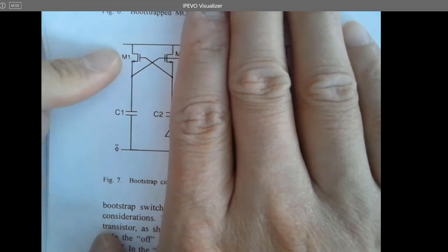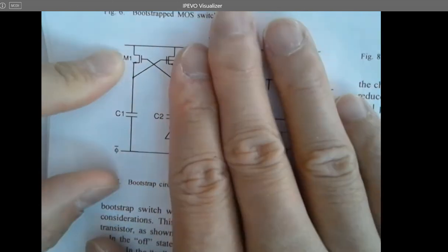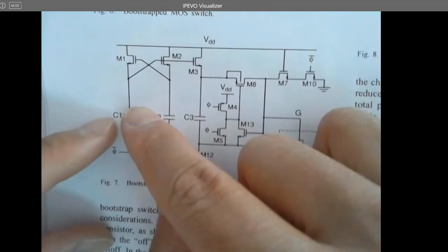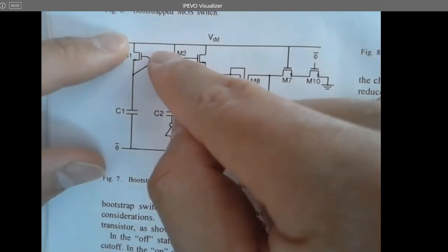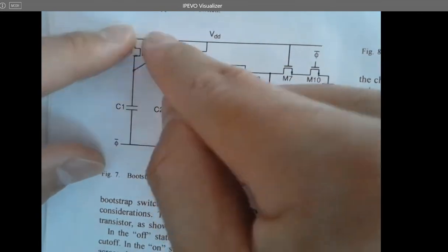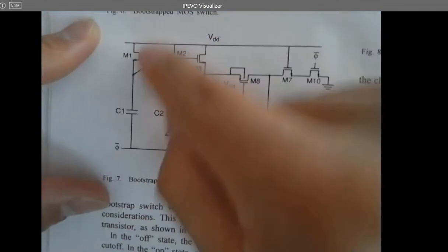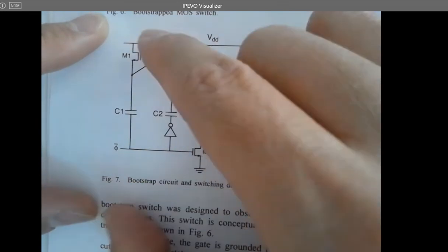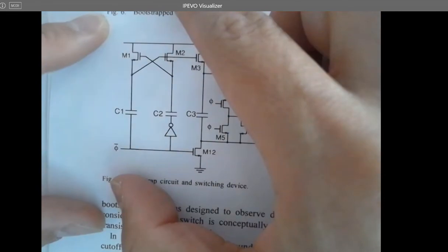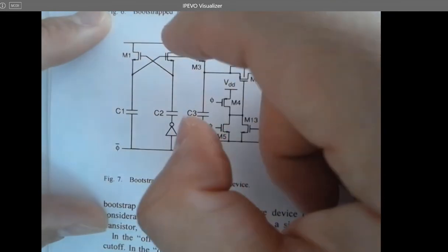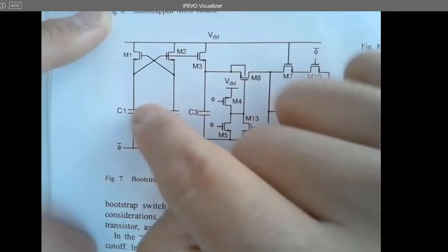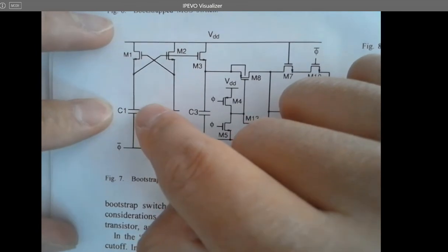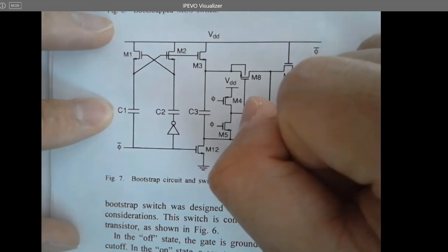And where to source all the positive charges? From VDD, right? Because here's the power supply. Whenever this is pulling charges down, you can imagine all the positive charges will be pulled down to here as well from the VDD. So it's just one current flow. It only happens for that transitioning period, the edge, right? Not the DC constant. Once DC is stabilized, all the charges will be stabilized. It's not changing anymore. So for the capacitor, it's only happening at the edge, right? So when this is pulling, current will be dumped into the top plate of the capacitor at the same time. So what's the voltage that will be here after that? After a few cycles, I should say.